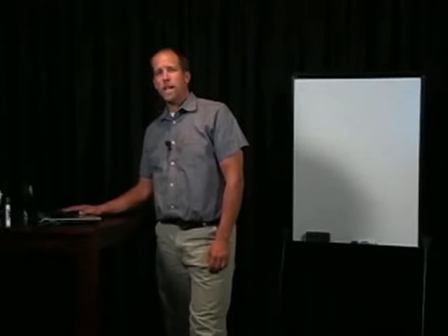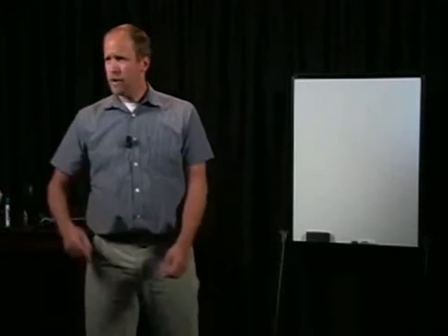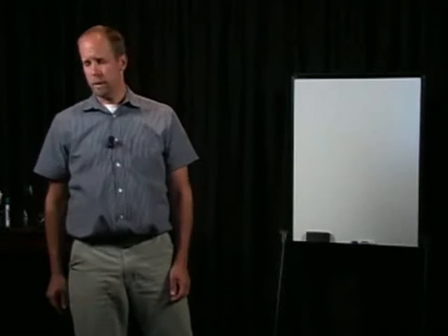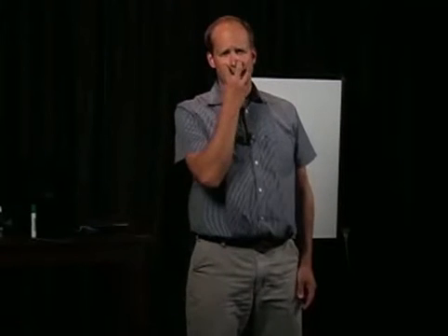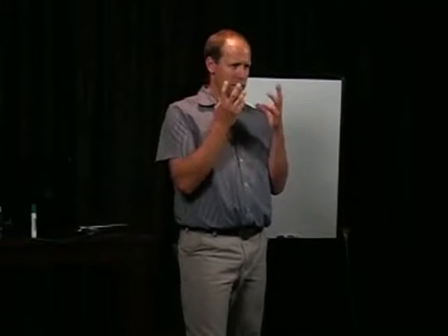Other inspection tools and equipment. Mask and a respirator. If you touch mold, you're disturbing it, and you may be putting mold spores in the air. If you're in a crawl space, who knows what's in the dark crawl space? Get a respirator. The N95 ones are, in my opinion, okay. You need at least a lower face respirator. A full face mask respirator protects your lungs and your eyes.